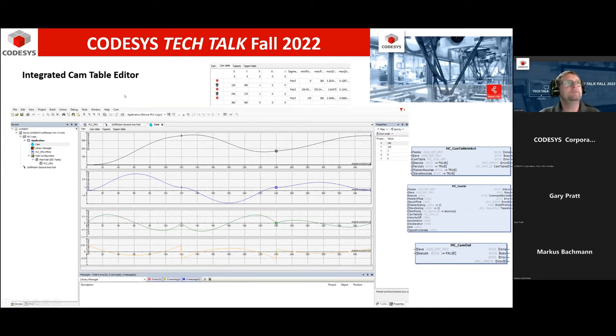So I was talking before about camming, just a little bit ago. The thing I wanted to show is that we have a very nice graphical user interface for this, in which you can actually drag these points. You can see here I have these little points, and you're able to drag them up and down. As you're changing this, or possibly changing the velocity or the slave acceleration or jerk, you actually see your profile begin to change.